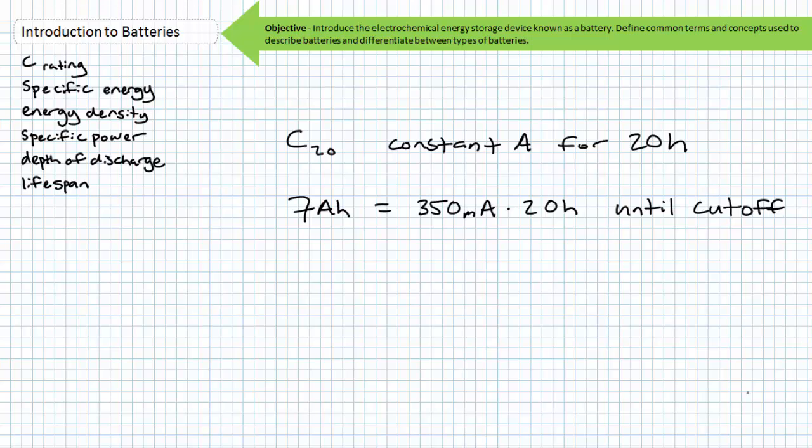First, one must inspect the datasheet of a particular battery to determine which C rating the nominal energy capacity is meant to represent. Again, the nominal capacity of a battery is a snapshot for a particular discharge period, or C rating. Ordinarily, most nominal battery capacities are rated at the C20 rating. However, batteries central to off-grid storage are often rated at the C100 rating, meaning the nominal capacity is determined over a longer period of 100 hours. Current draw for the lengthier C100 rating is proportionately lower than a more rapid discharge like the C20 rating.